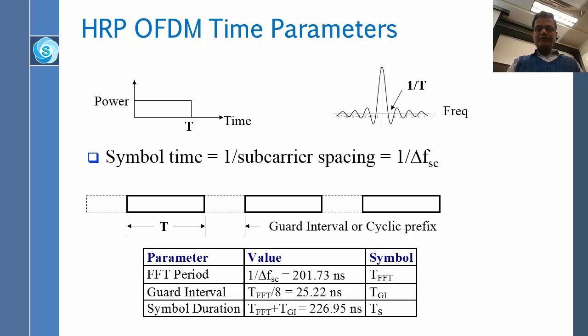Okay, actually I might have a picture. I tried to draw a picture. Right here is the picture, which explains that. So let me explain this. The subcarrier, even though we show it as an impulse, is not an impulse. It's a square wave. A square wave in time has a frequency spectrum like this, where there is a peak, and then at 1/t it is 0, and then again it is 0 like this, and it slowly dies down.